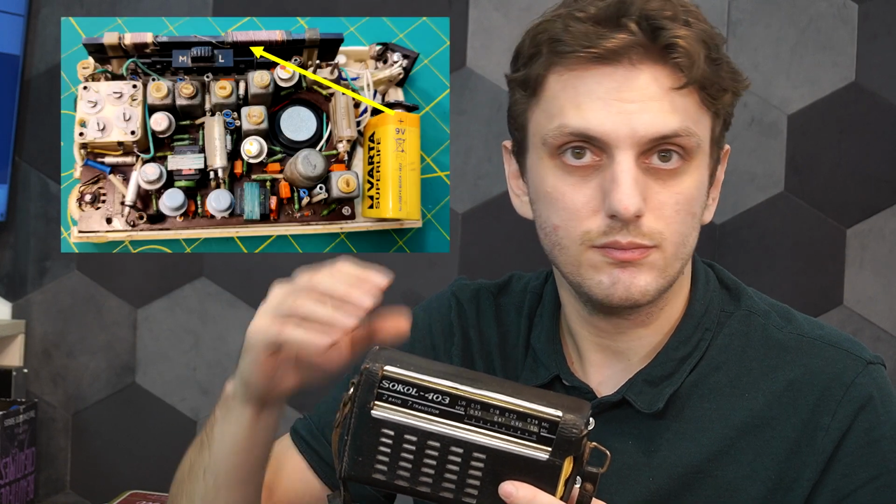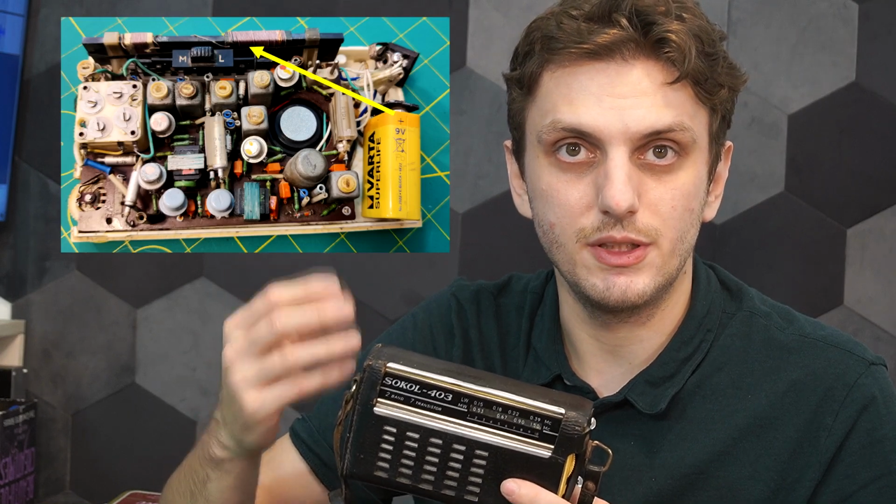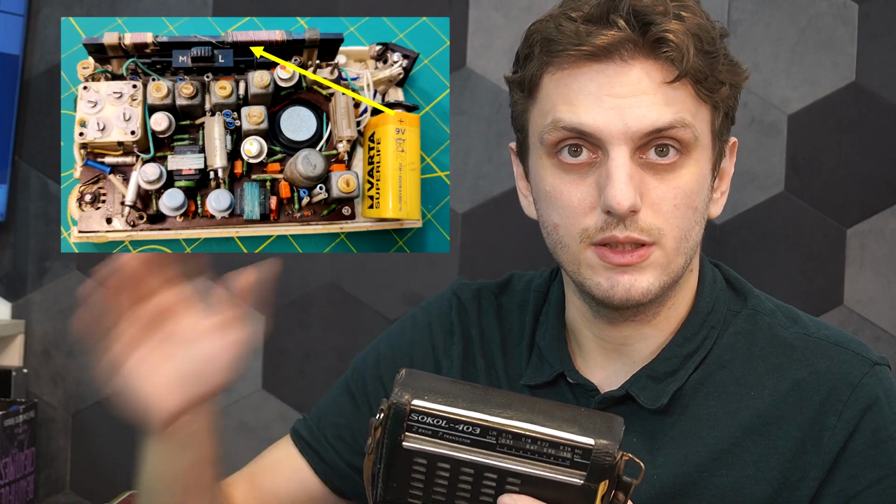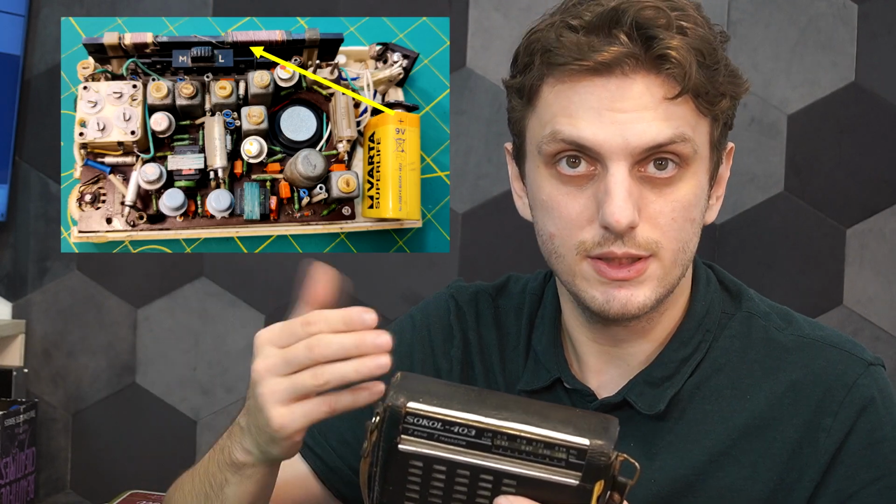And luckily for us, most of the more modern radios, like this one designed in the 60s, have a ferrite rod inside of them. So the main receiving coil is placed on a ferrite rod, and this enhances its sensitivity to magnetic fields. So if we can couple the signal coming from our circuit to this, we will have a pretty good transfer method. And to achieve a proper transfer through magnetic fields, we need to build an inductor.